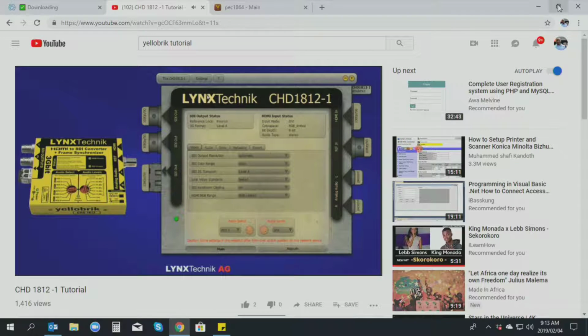So again, I'm not going to go through each one and describe each one of these settings. You can do that yourself. That's not a problem. But I'll show you what settings are possible. One I will explain, because this one is important, is, as I said before, there's no image scaler inside the module. It's transparent. Whatever's on the input is converted to the corresponding SDI resolution on the output. Now, typically what would happen is there's EDID negotiation that goes on between two HDMI devices when they are connected.